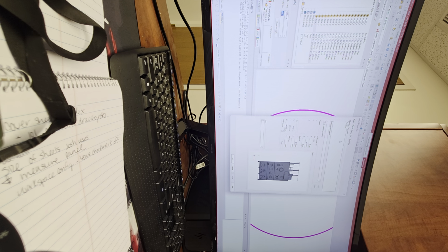Okay. Right. So same thing from the DIN rail's perspective. The DIN rail itself has its standard. The DIN rail itself will have a slot line called TS35mm, and that's how you look at it from a DIN rail's perspective, while everything else mounts onto it. Same thing with how this component can go on a DIN rail.